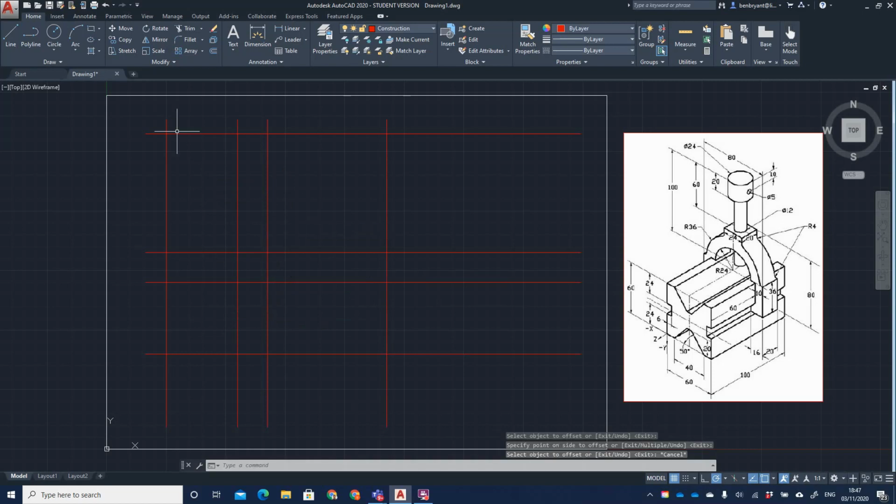I've set all three views so that the parts are 25 mm apart, which are these gaps here. Okay, now I'm going to start putting in the features that I know using the offset command. I know this top line here running from the top is 10 mm wide, because obviously it's 60, take out the V, which is 40, and then either side will leave me 10 mm. So I'm going to put in 10 mm to offset my first line on both sides.